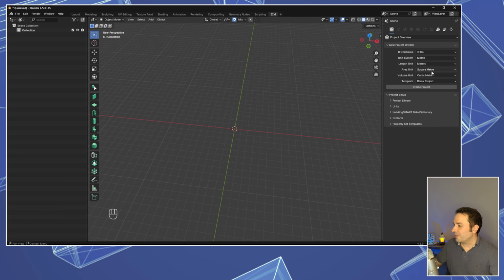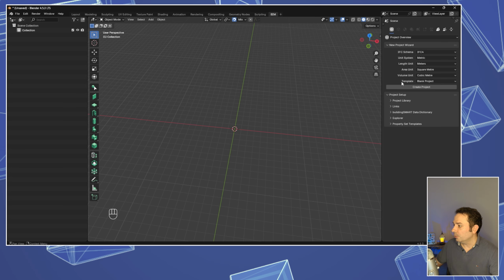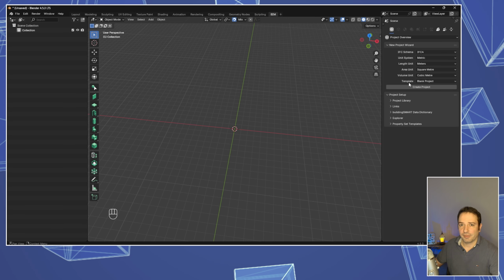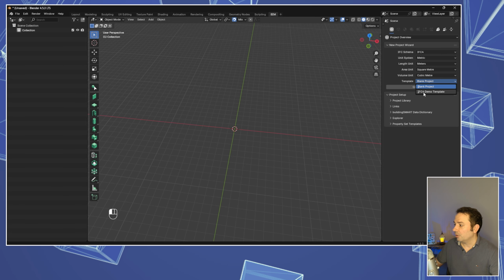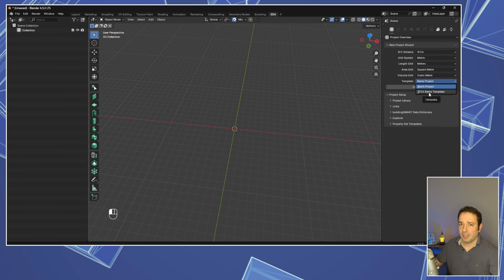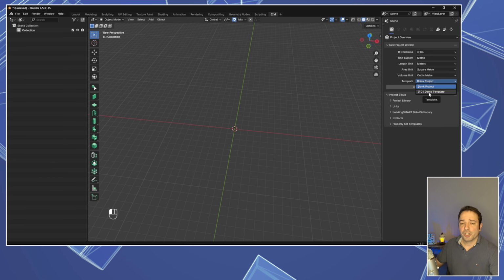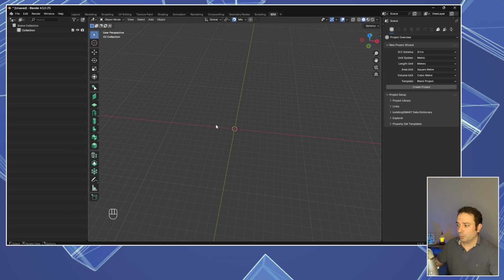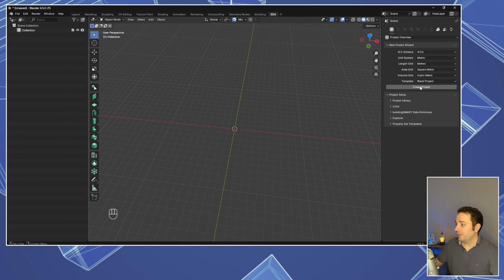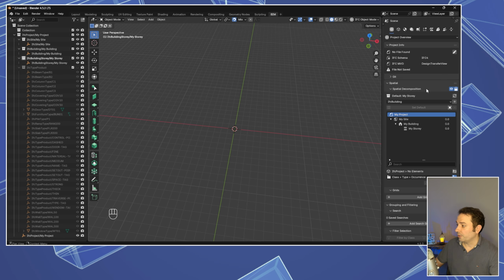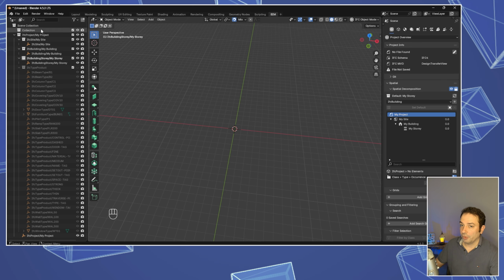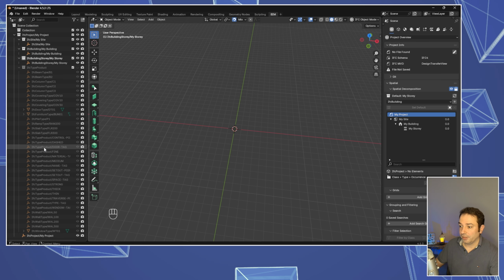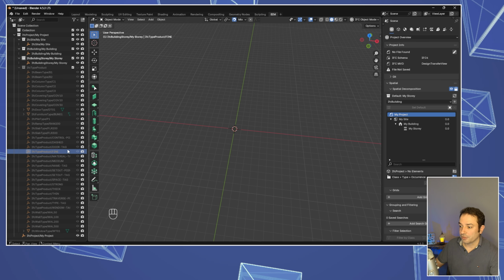The next thing that I'm going to do is to change the template. This is a really important step. I'm going to start using the demo template IFC4, and it's going to give us a lot of IFC objects that we can use straight away to edit our building right here in the scene, and create project. You can see that there is a lot of stuff that has been loaded in our project, which are basically the IFC elements that we are going to use later on.